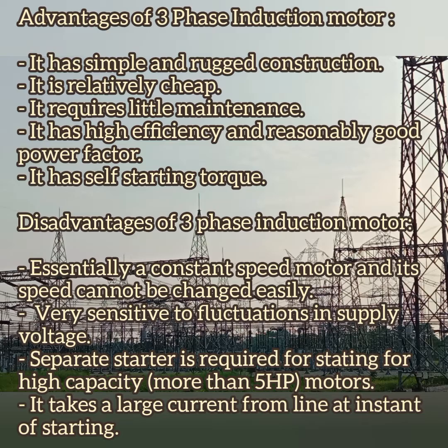If your load is higher, automatically the speed of the induction motor is reduced. Next, it is very sensitive to fluctuations in supply voltage, the same as the earlier point. Then a separate starter is required for higher ratings.